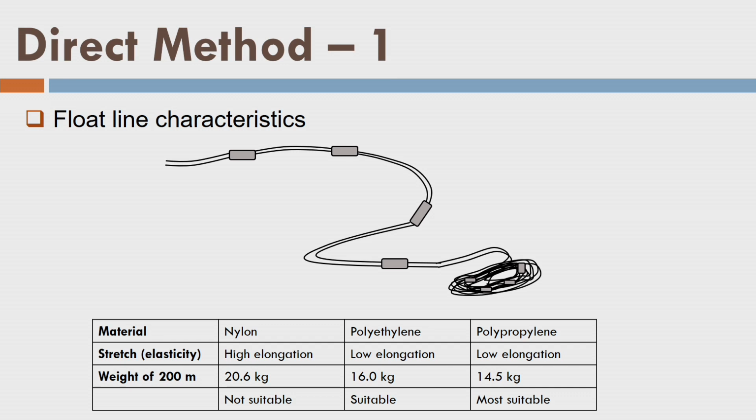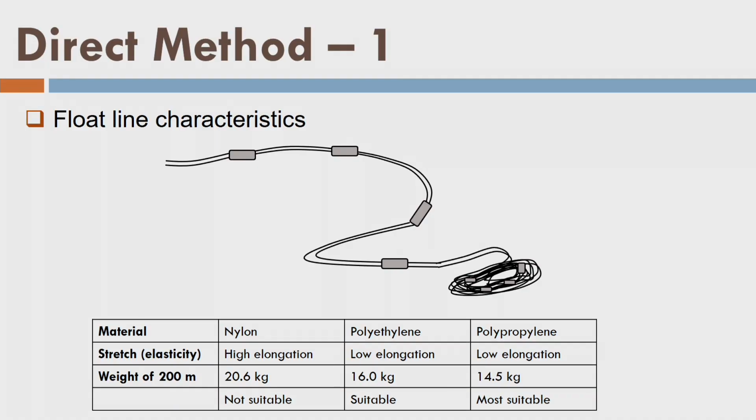with the help of a nail. With the help of this nail, we take the float line which is shown here on the screen, which is a kind of graduated line, and it has buoys. We stretch it between the reference mark that we have already marked on the shoreline, on the reference line, and we stretch it across the river.